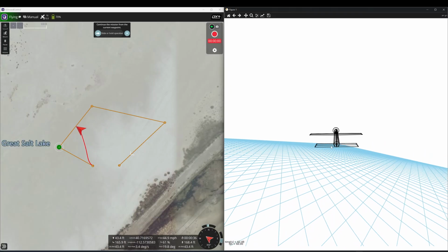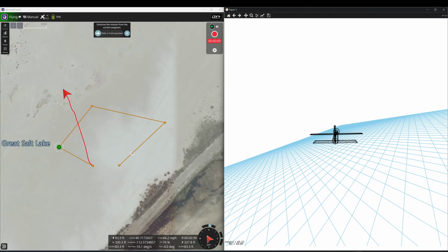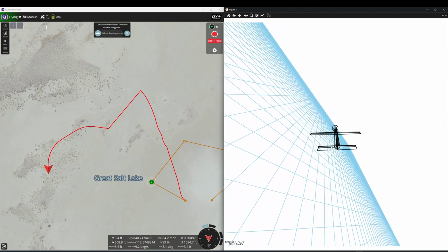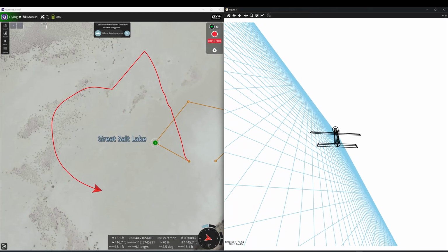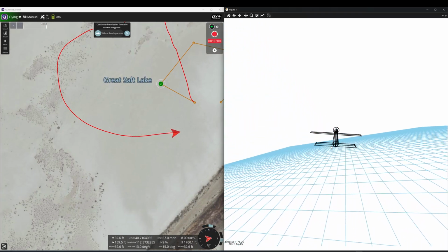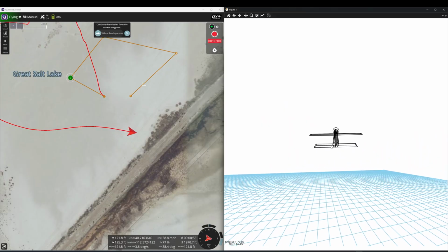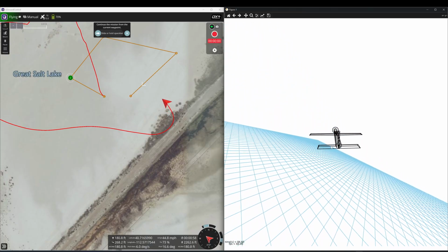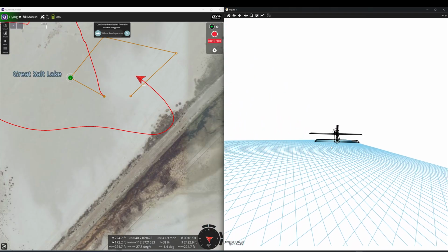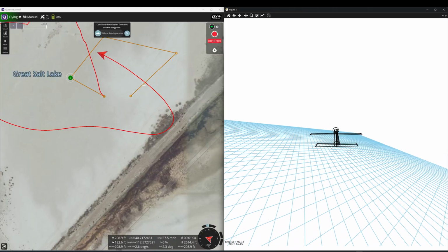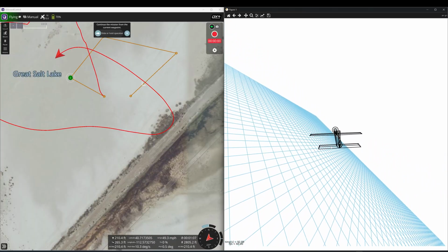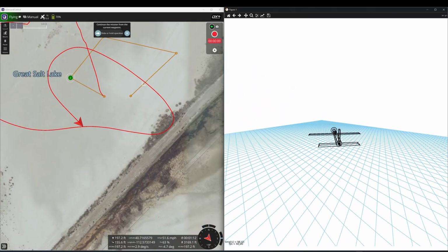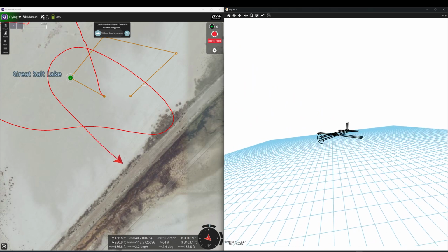Okay, MAVRIK just launched the vehicle, and we're able to fly around now. I just have a USB radio plugged into my computer that you can set up QGroundControl to use instead of a normal pilot radio receiver into the PixHawk, but you can do either. See, I'm flying around, so our design is pretty good, not too bad. I did tune these values beforehand to make sure this actually flew well. But our control surfaces are moving the correct way. Our motor is working.